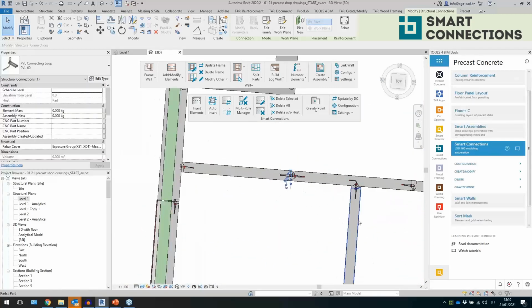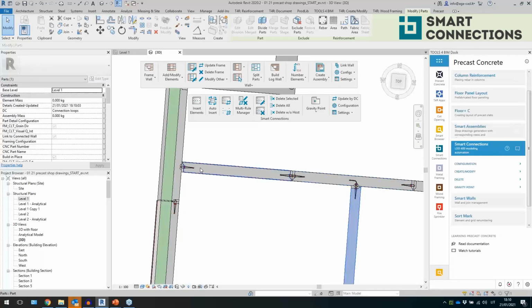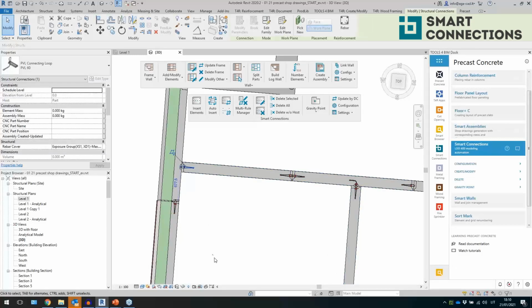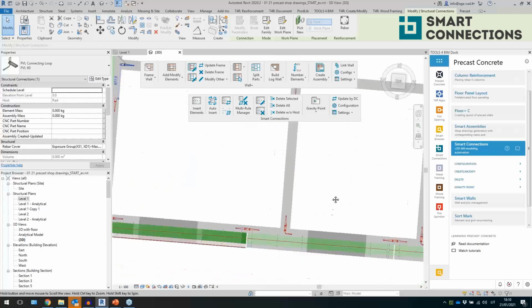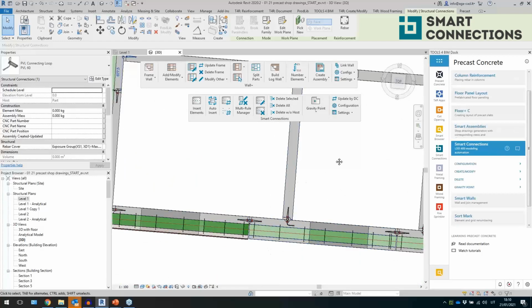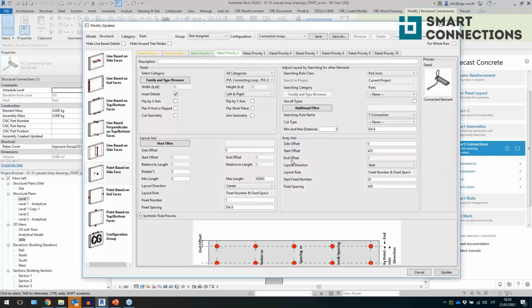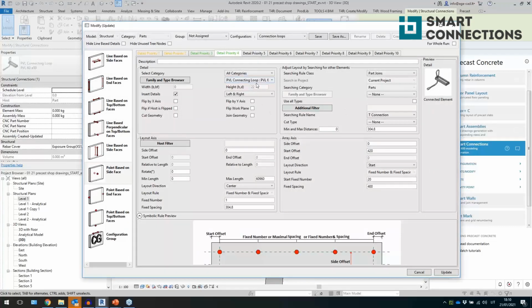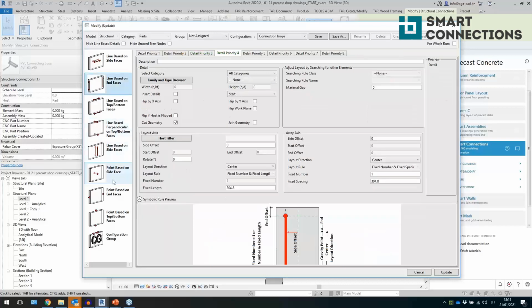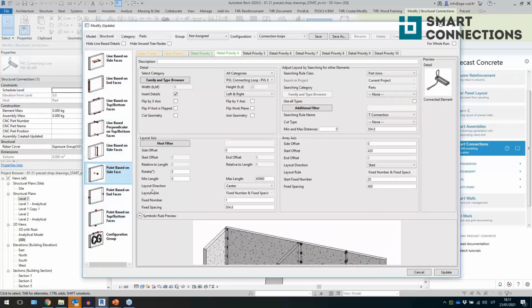So if I have an intersection with another part, I have this element. Then if that's the end, I have this one. If again an intersection and so on. So I have these kinds of elements. If I click on one of them, I will show you how the configuration window looks. So that's the way it looks. So I have here line-based families and point-based families, which I can insert with this tool, and I can use it on parts, on walls, floors, and so on, right?